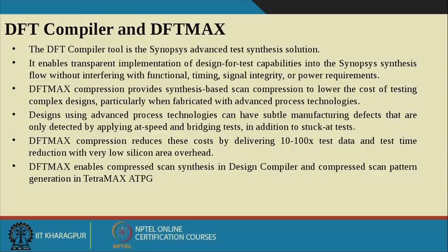Designs using advanced process technology can have subtle manufacturing defects that are only detected by applying at-speed and bridging tests in addition to stuck-at tests. DFT Max also reduces the cost by delivering 10 to 100x test data and test time reduction with very low silicon area overhead.